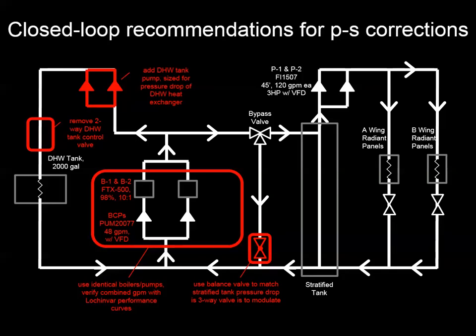So based on that same design drawing, we realized that we had missing balance valves. We had essentially dual secondaries, where one of the secondaries didn't have pumps to do flow control, and also we had some of that pump interaction. So the design concept was to run the boilers and the boiler pumps together to meet full load, but when we looked at it on the pump curves, we were able to determine that we weren't going to get the full design flow through those boilers and out to the primary system as indicated.